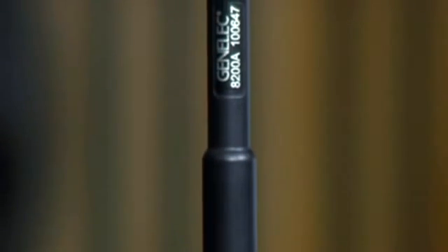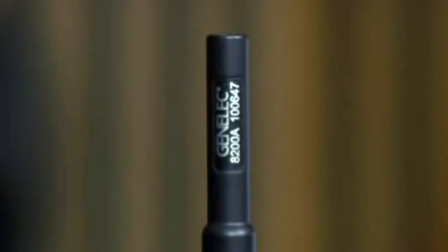The Genelec DSP series is based on the revolutionary technology of the 8000 series, but with a twist, the addition of digital networking and an onboard DSP. From within the Genelec Loudspeaker Manager software, we can construct a network of up to 30 loudspeakers and subwoofers and control them individually or as a system. A powerful feature of this system is the automated calibration, AutoCal. With this Genelec microphone, the software can measure successfully every loudspeaker and subwoofer on the network, and then calibrate them individually or as a system for any given listening point.